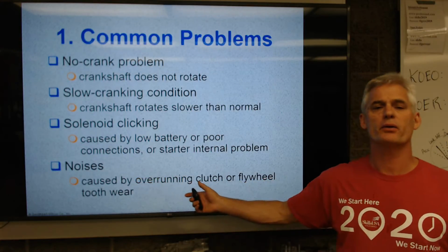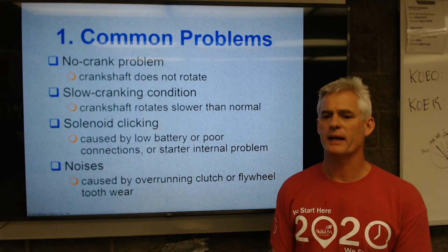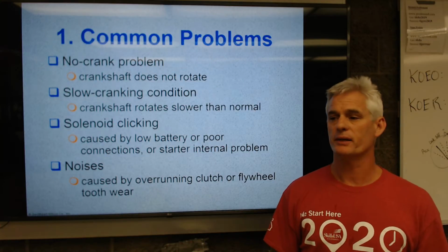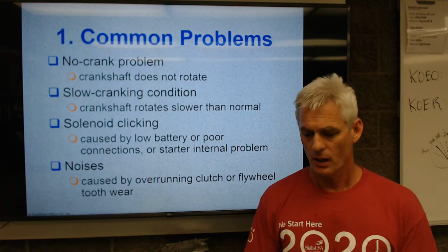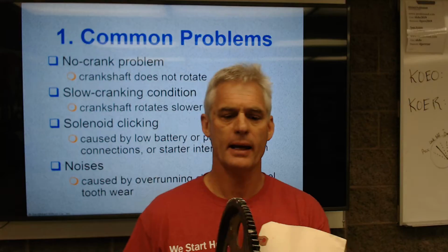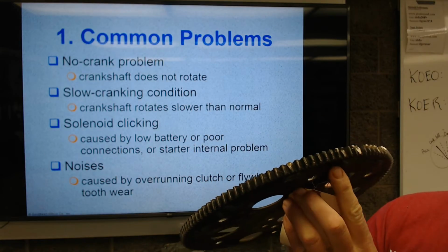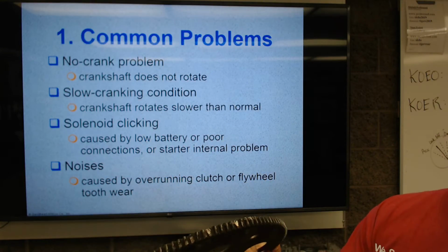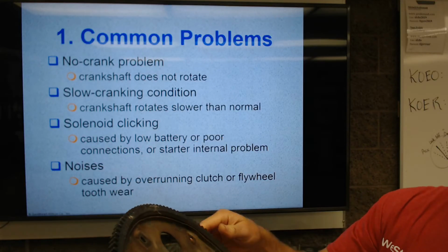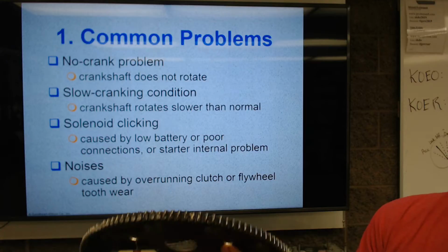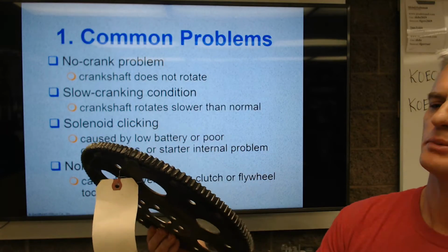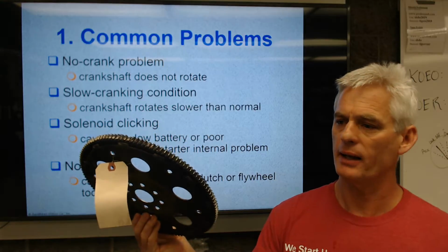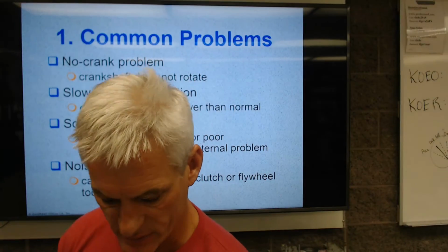Any other noises are caused by an overrunning clutch or a gear that's chirping? Sometimes we have to replace the gear on a starter. Sometimes there are actually shims. You can shim some starters away from the engine to help take care of some of those noises. I'll pause this for a moment. I did that long enough so you could see the teeth on this flywheel ring gear that are chewed up pretty bad. There's another spot on here in addition to this tooth being gone there and that one being gone there. This thing's pretty rough. That will be caused by a problem on the starter gear or the flywheel, but in any case, it's wearing the flywheel out, and something needs to be solved in that scenario.